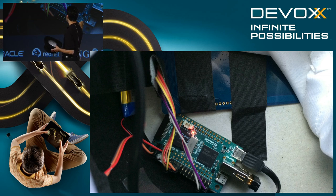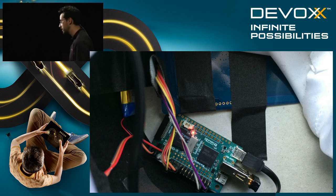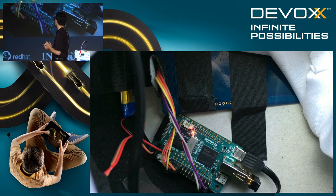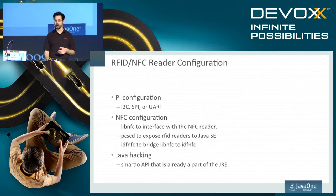A single USB port, which I'm using for the Wi-Fi adapter, and it also has built-in circuits on the board for power charging. So there's a little battery on the top left side there. That's what's powering the Pi hat. And it will charge that whenever it's plugged into USB, and also allows you to run it wirelessly. So I'm going to pass the hat around as well for you guys to take a look at. It's partially open. If you just peel the fabric back a little bit there, you can see the internals of the wearable hat. And then at the top right there, you can see the RFID sensor, which is how it's actually picking up the cards. It'll work on either side. You can drop cards in the hat, or you can flash them across the back of the hat as well.